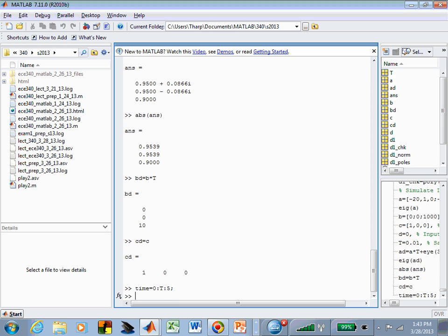That's now my time axis, and let me build an input that is the sum of something that I want to pass, which is a 5 radian per second signal. That's in the band pass region of my low pass filter. And now let me put something that's not quite as big in magnitude, but at a higher frequency. Let's put it a decade beyond the cutoff frequency, 20 t. So this now is representing a noisy input signal.